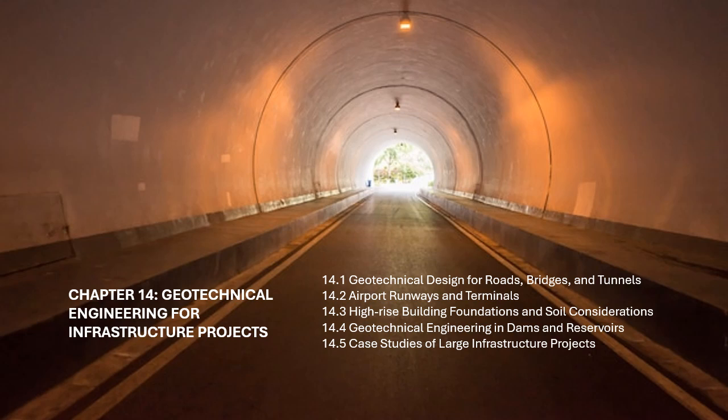In areas with weak soils, soil improvement methods may be applied to enhance the bearing capacity and reduce settlement. Techniques such as grouting, vibrocompaction, and geotextile reinforcement are commonly used to stabilize and strengthen the soil, making it suitable for the heavy loads of high-rise buildings.